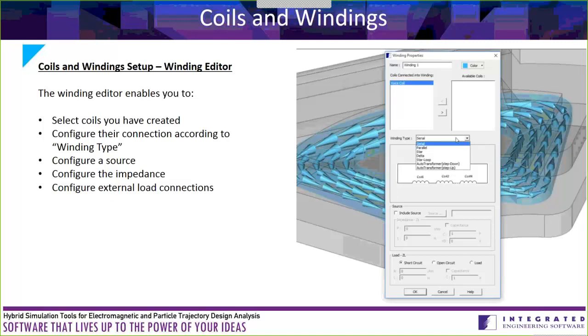One heads up that I'll give to users who appreciate the benefits that I mentioned earlier of the boundary elements. In 2 dimensions, this method works for either finite elements or boundary elements. In our 3D, it presently only does work with the finite elements. So if you prefer working with the boundary elements, this is not an option right now, but of course that is something that is on our list of improvements to make to this.